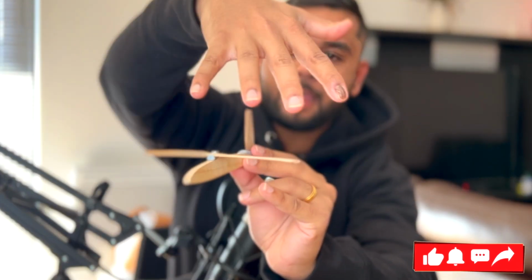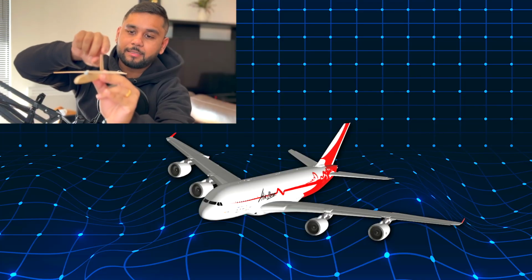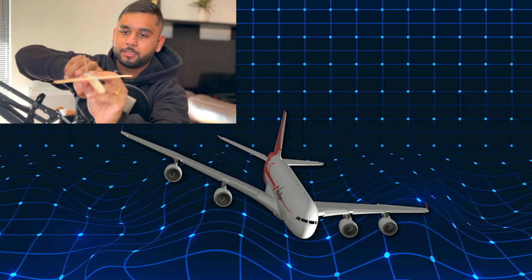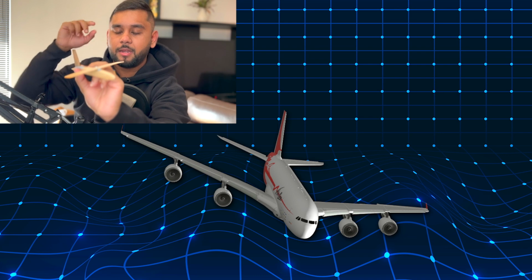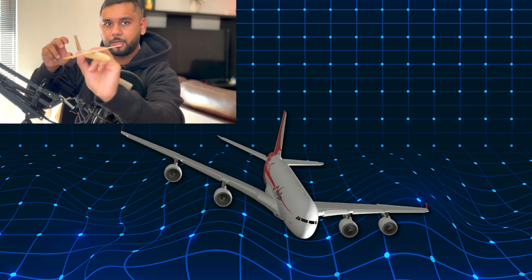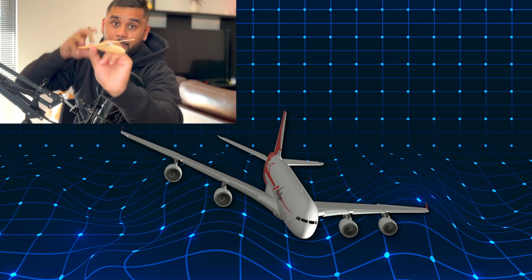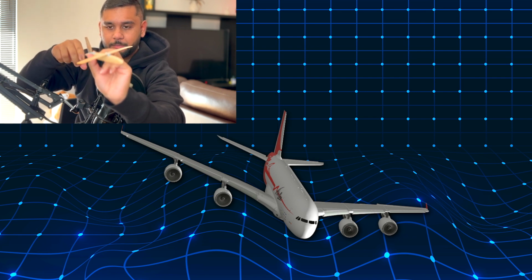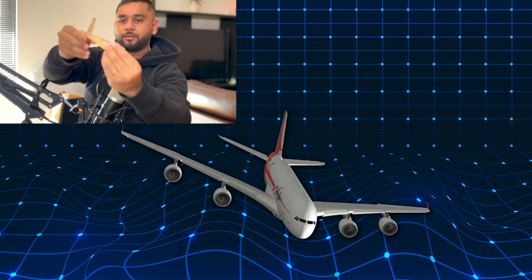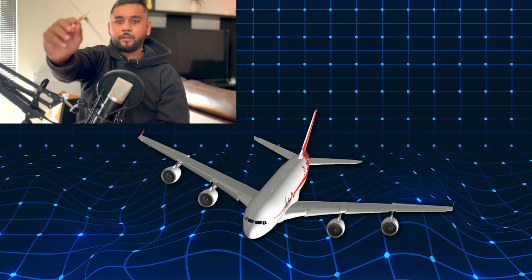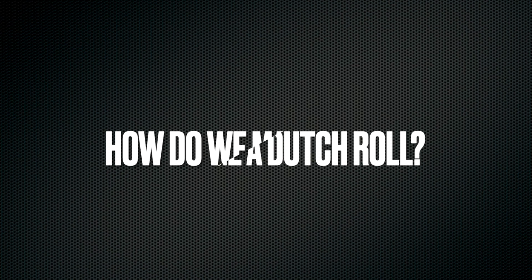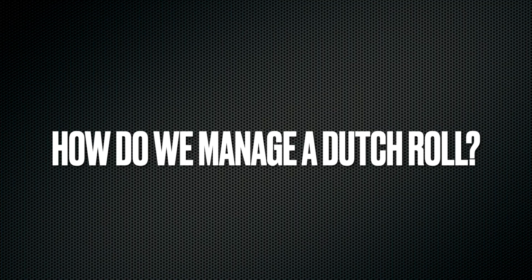As you can see, the air will come from this side of the vertical stabilizer compared to this. So this will have a higher angle of attack. What this does is it actually pushes the aircraft this way. Now if the lateral stability is strong and it overshoots, this process will continue in a cycle and not that way. So this will happen to this aircraft.